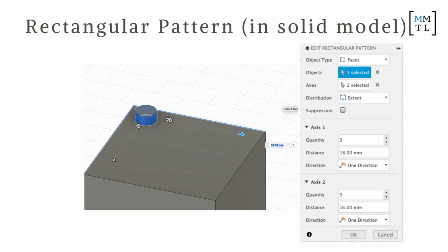And then you pick the axes that you want to pattern it on, so you want to select the top two or just the Y axis. And then choose the rectangular pattern. So you can go back to your project now. Yeah, the reliable way is, you see how there's an axis there, right? She's going in the wrong direction. Okay. It doesn't really matter, it'll just go negative.